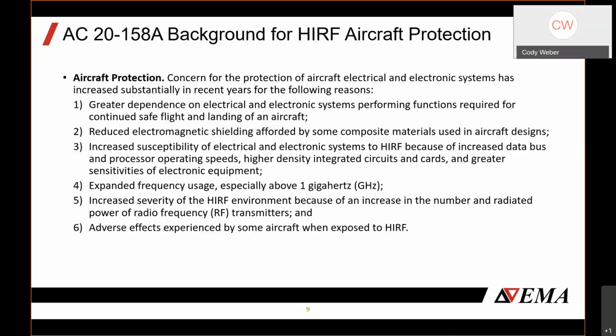And over the years, as our technologies have become more advanced, with an expanded frequency range and new and novel materials such as composites, glass fiber, epoxies, and other radome materials, it changes the coupling response of the aircraft compared to more traditional metallic aircraft. So it's certainly a focus of authorities, with an emphasis on safety, for aircraft to be able to certify to the HIRF environment.